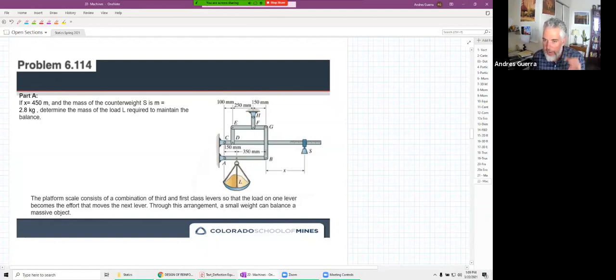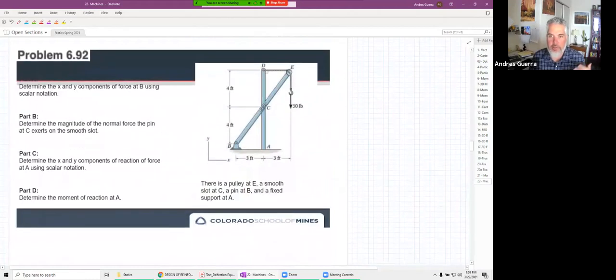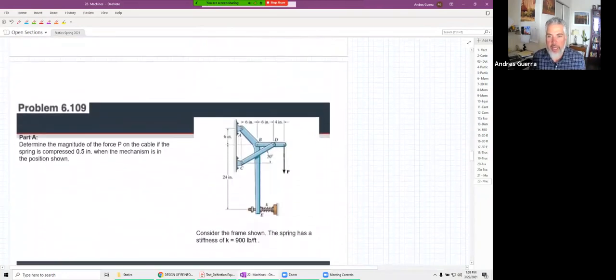We just identify all the different rigid objects and then ask ourselves, okay, what if we drew an FBD of that? What would we have in that FBD? Would we be able to solve for anything? That's our process for all these problems. This next one too, let's look at what about an FBD of this rigid object? What about an FBD of the whole thing? What about an FBD of this other rigid object? That is the best way to approach this.